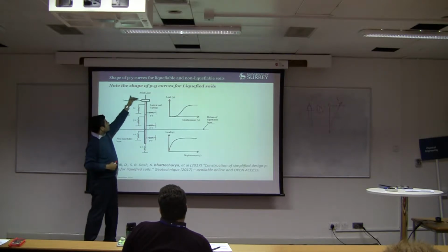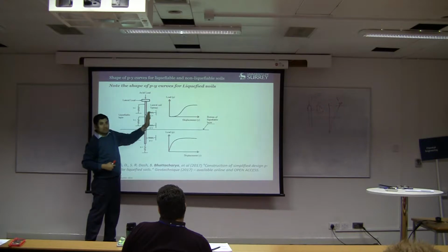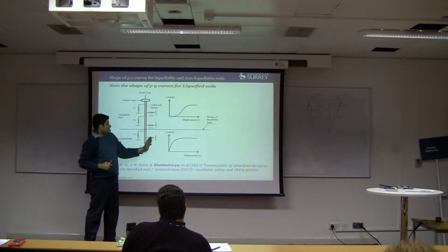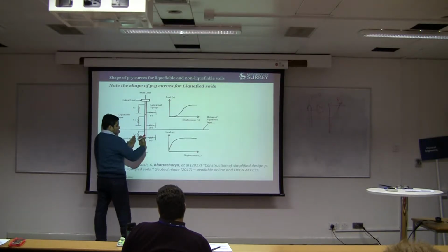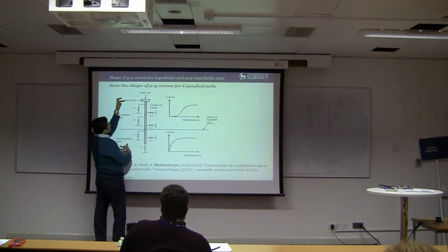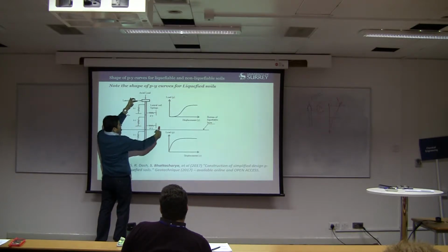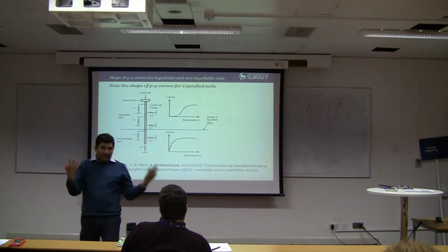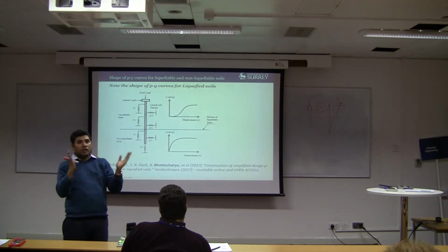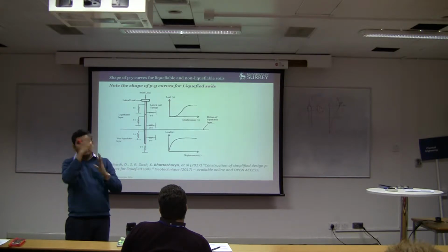When you apply the load, this thing will move more, this thing will move more, this thing will move less. Yeah? Now as it moves, it then generates some resistance. So this lateral load has to be balanced by these forces. So what the program does, or what this balance does, is try to find out a compatibility of displacement and loads.